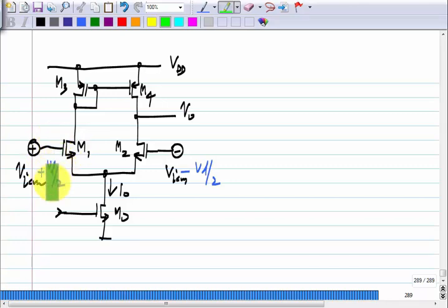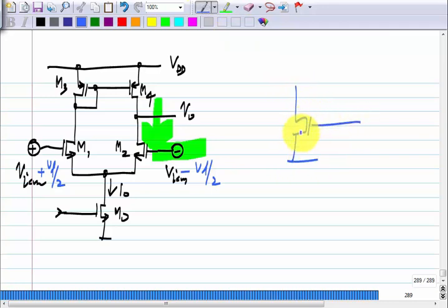this gate voltage is rising because VD is positive. Okay. There is always a possibility that M1 goes into triode region, but that is what I was saying earlier. This VD is so small that we do not consider those possibilities, we do not have to worry about those things. Okay. The big change in voltage is only in the output voltage. So, what happens as the output becomes smaller and smaller, the gate voltage of this is nearly fixed, again VD is very small, right. So, the gate is fixed at VICM of M2 and the drain keeps falling.